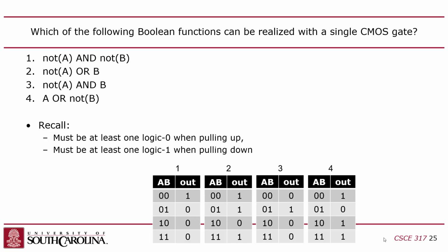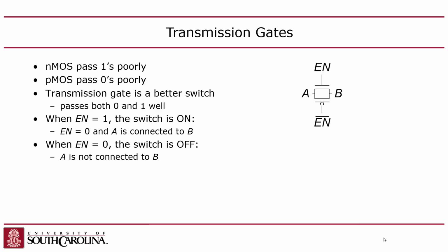I can't give it 1, 1 and have a 1 output, because the PMOSs are responsible for giving a 1 output, and PMOSs are not activated on 1. So this row doesn't work. This one row disqualifies. That row's fine, and that row's fine, but there's one row of the truth table that makes it impossible to implement with CMOS. So that's basically how you solve that.